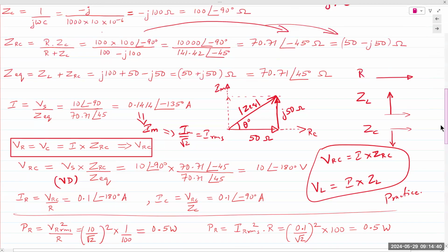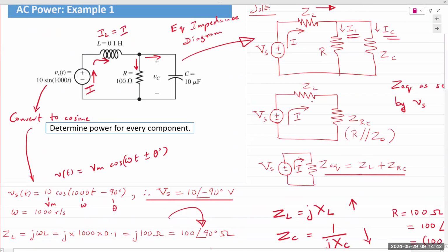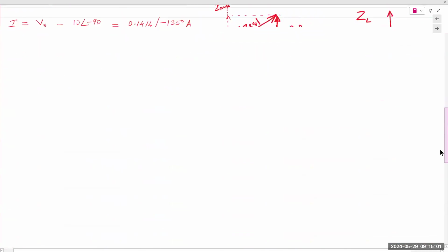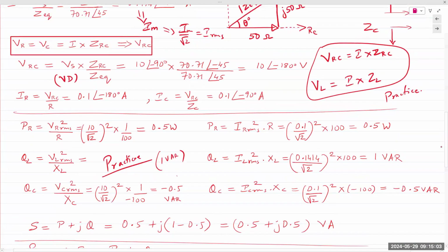Again, multiple ways to solve the exact same circuit. These are 2 impedances connected in series. So voltage gets divided across the 2, depending on the values of these impedances. You can apply voltage division to find the voltages across the capacitor and the resistor directly. So the equations are all there. No matter which approach you choose, your answer should turn out to be the same.